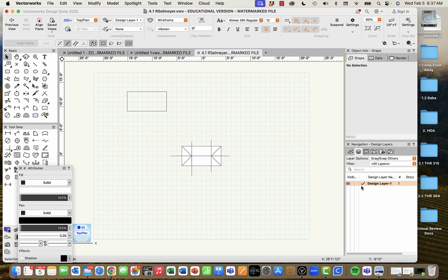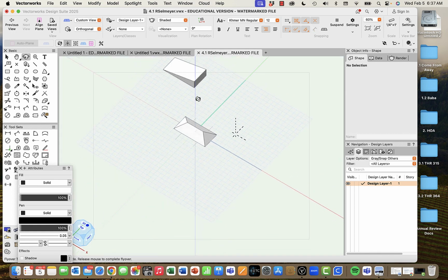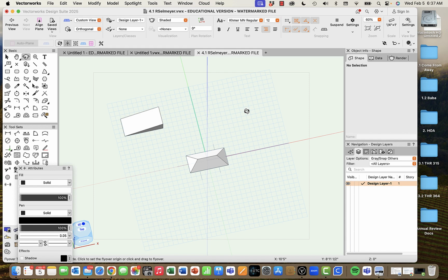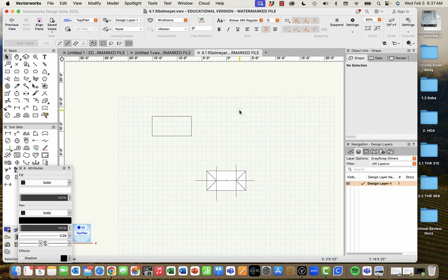When we convert that 3D modeled program into pages that get printed for a drafting package, that's what we're going to focus on in this video. So to the right of your design layers in your navigation, you can see that this one that has sort of the border and the little title block, these are your sheet layers.